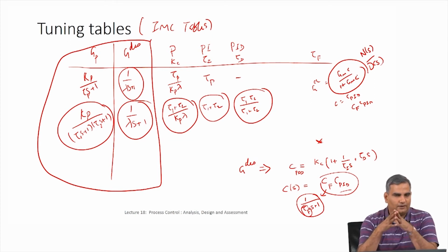So that is the first part of it, and then we saw how to analyze this, what are the advantages and disadvantages of these controllers through the simple final value theorem. I showed that if you have a P controller, you will always have an offset. However, I also showed for some simple examples how the P controller is quite fast and reduces the closed loop time constant very efficiently when compared to the open loop time constant. So P controllers are quick acting, easy to implement.